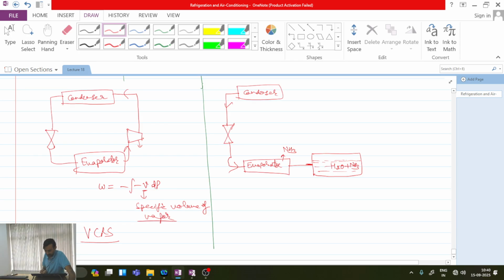So what will happen in this solution of water and ammonia? Let me connect it from the top. The vapor is entering, and along with that I am using a cooling coil over here, which is rejecting heat from this chamber at the rate of QA. Continuously this vapor will keep flowing and condensing. After condensation it will form a mixture with a rich concentration of ammonia.